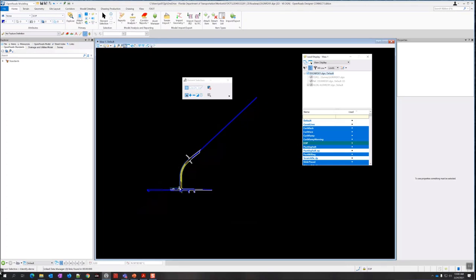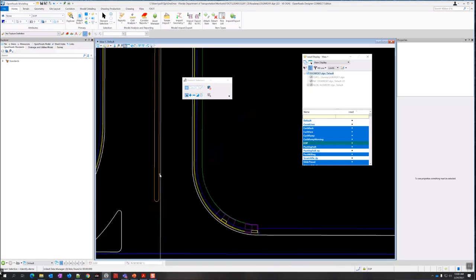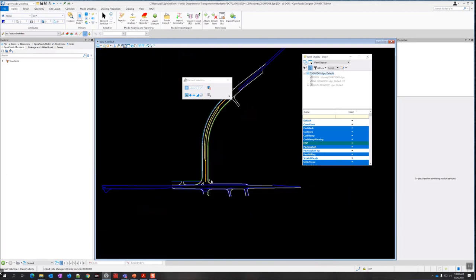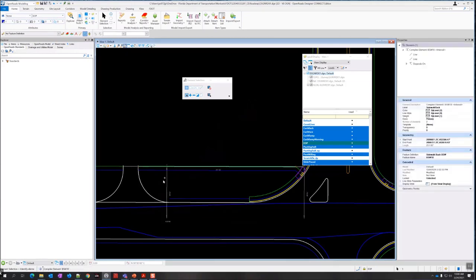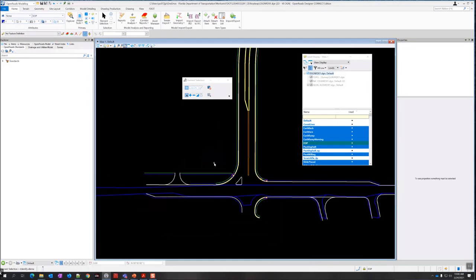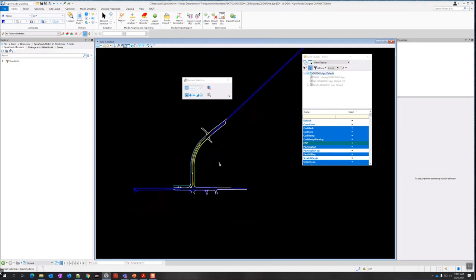So now I just have proposed lines in here. I've got my pavement milling, all of my edge of pavements, traffic separators, all these lines here. And these are great. These are all pretty much civil geometry. They all have feature definitions, intervals, and all kinds of rules and intelligence. So you can see if you select one of them, it's ruled off the center line. And this is definitely the way we work in ORD. That's to be expected. But for what we're trying to do here, we don't want any of that. So what we're going to do is create a fence.